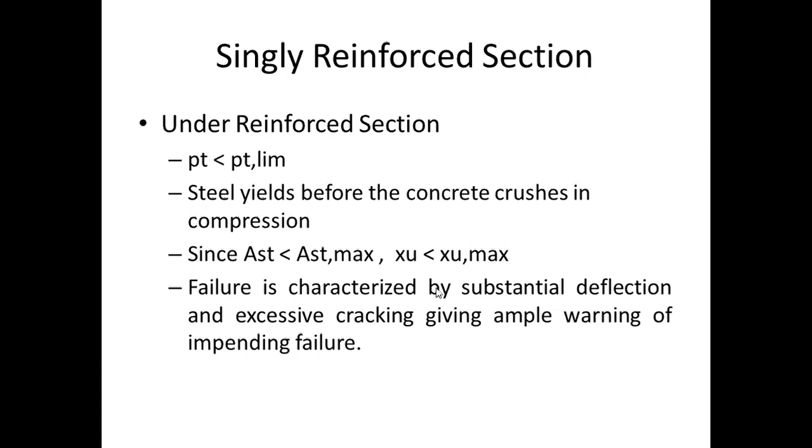So let me summarize. In a singly reinforced section, there are three cases: under reinforced section, over reinforced section, and balanced section. The three sections in each case are going to be there. Generally, people design only for the under reinforced section and balanced section. Let me see about the under reinforced section.